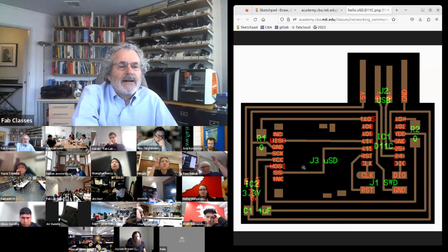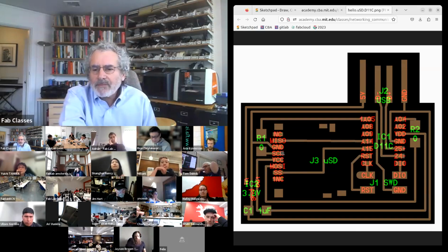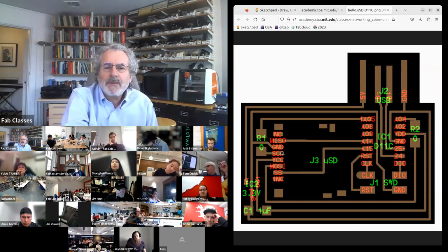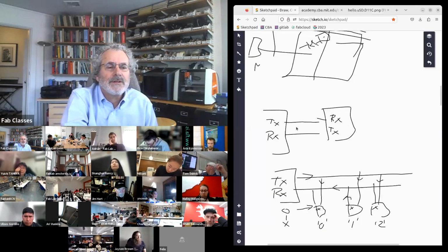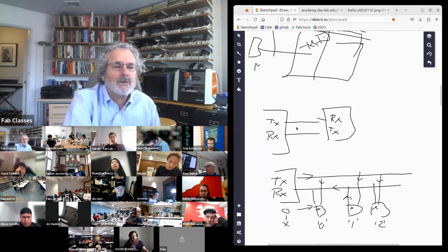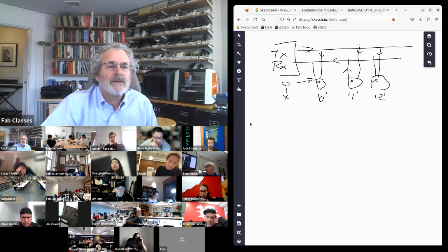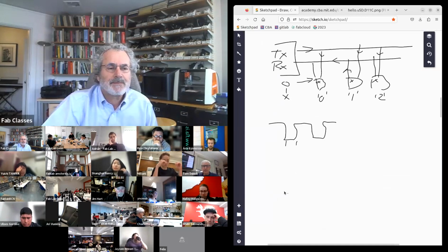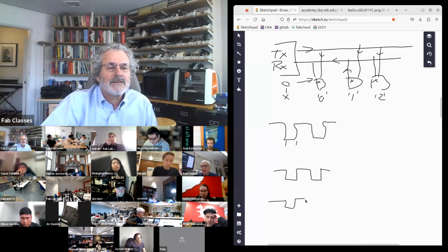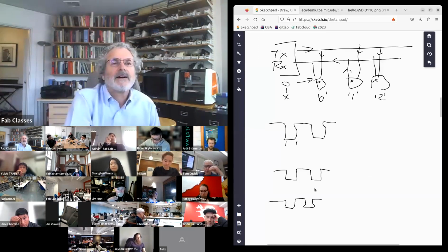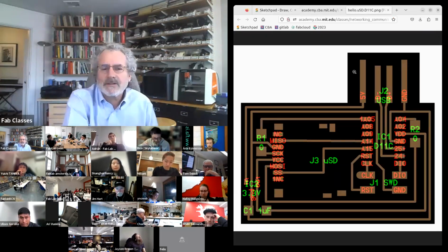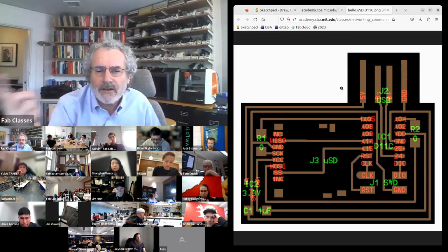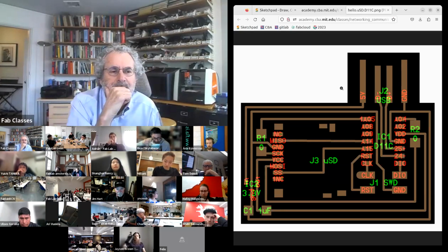And then there's a clock pin. And in SPI, so in RS-232, you just simply start toggling bits up and down, and you agree in advance on the duration of the bit. For SPI and for I2C, which we're about to talk about, in addition to the data lines, there's a clock line. And so you toggle the clock line to tell it when to read the bits. And so you don't need to guess when the bits are. The clock line tells you when the bit goes by.